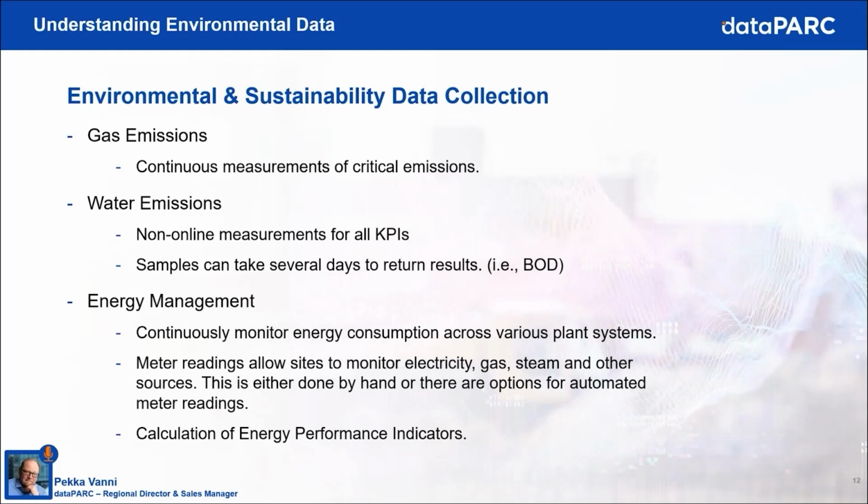The sample is held for several days, like 5 or 7, at a certain temperature until the tests can be done. The sample represents a certain time period. The collection cycle can be, for example, 1 day or perhaps a weekend. Then you have to combine the test result with the wastewater quantity of the collection period and calculate the actual biological oxygen demand. Doesn't sound straightforward, or what do you think?